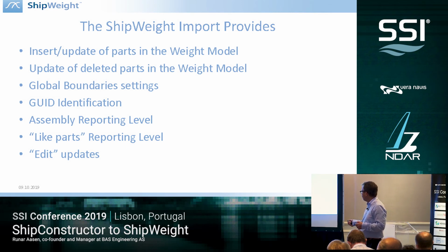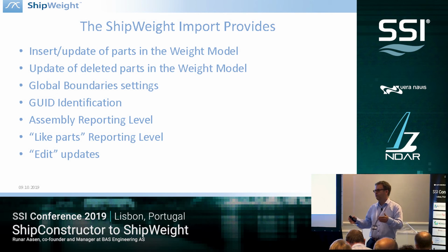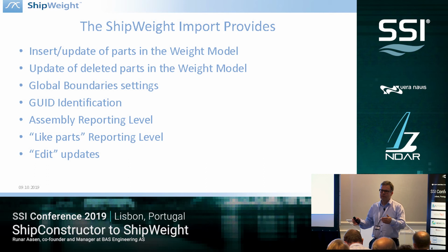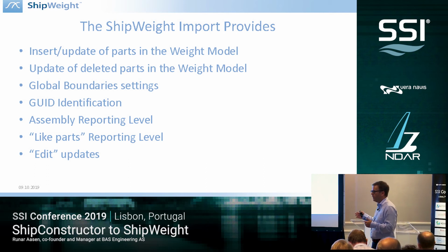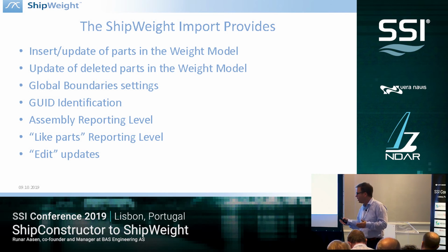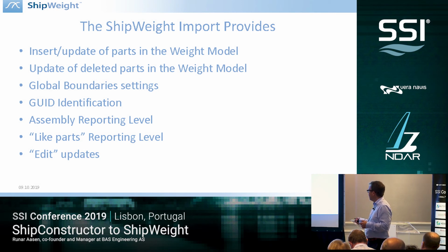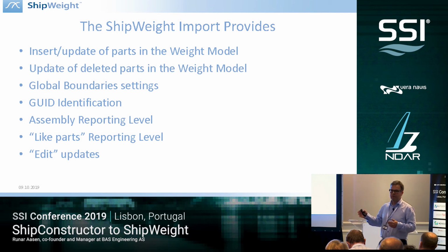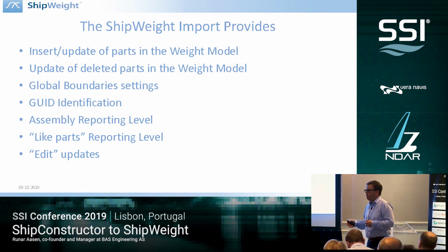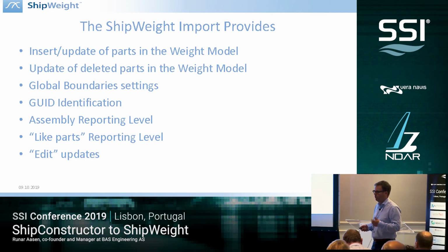Then we have a mapping file. These TSV files that you get from Publisher LT aren't static. They can be designed to fit the needs of your organization. And this means that we must also be able in Shipweight to adapt to however the TSV files are set up. So we have something called an XML mapping file in Shipweight that we can load and that knows how to interpret the TSV files. When that's done, basically you click the button, import, and Shipweight will import and update your model.